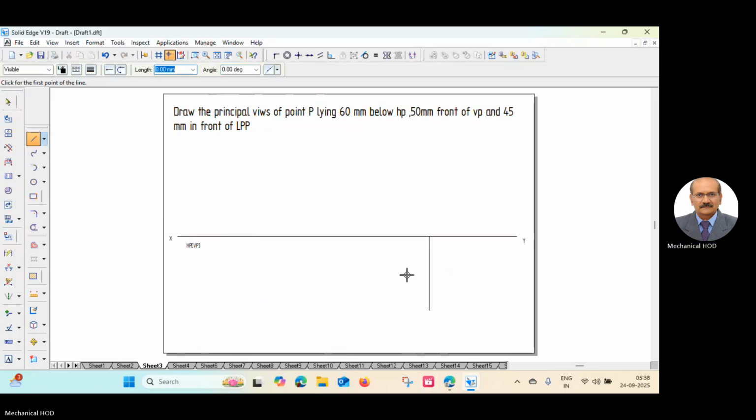Again, scroll on this vertical line. Reach the end point of this line, which means we have to select a point on the XY line. Left click, it is selected. Now the length is 50 mm. Type 50 on the keyboard and press the enter key. We have drawn two lines, one above the other. They are not visible separately because the width of the line is the same.